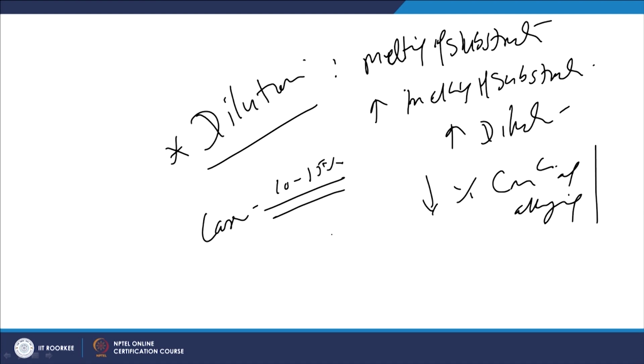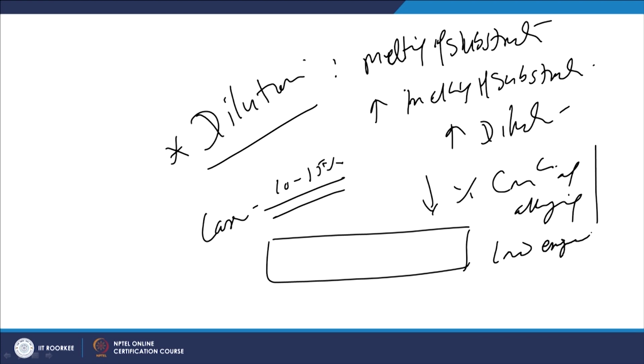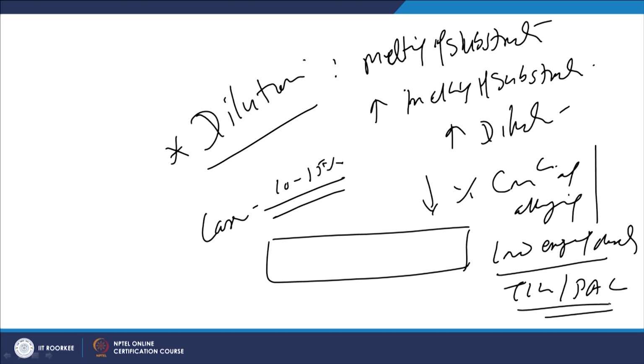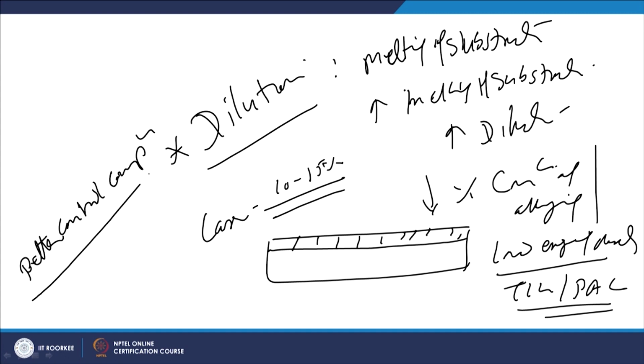and if we are melting the base metal up to a greater depth, like in case of the low energy density processes like the TIG, plasma arc, on those processes, the depth up to which melting of the base metal will be taking place will be greater, which in turn will be reducing the alloying concentration and increasing the dilution. So, we have much better control over composition by surface alloying in case of laser alloying.